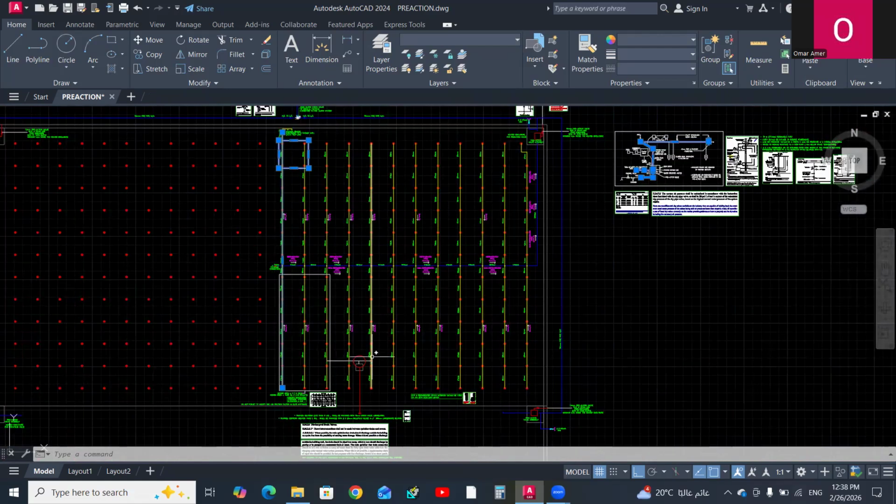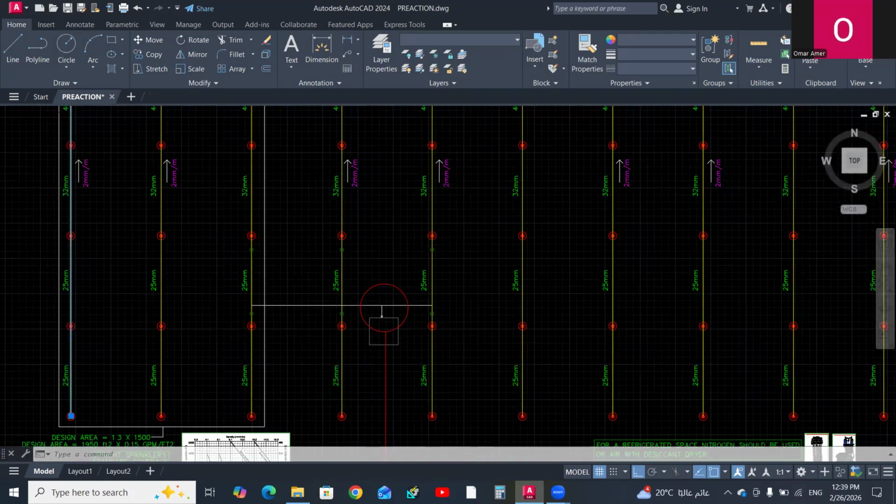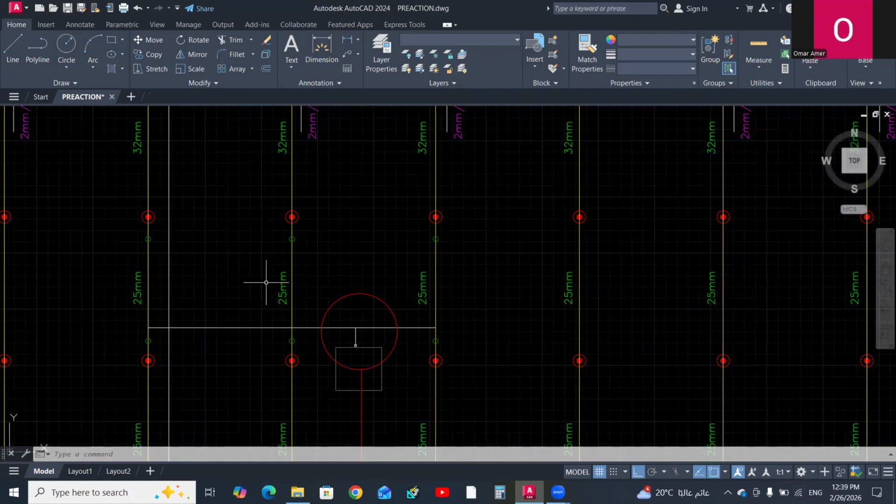Any trapped sections of piping due to coordination. Let's take an example. We have trapped sections, U-trapped sections. Drain points will be collected at these locations. You have to use a 1-inch or 25 millimeter connection to these trapped sections.